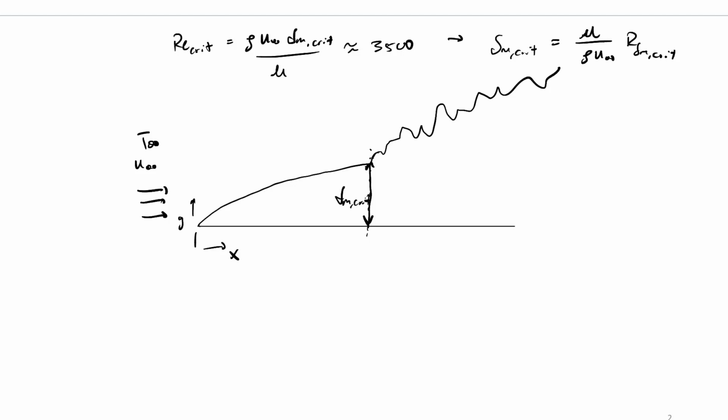It's sort of cycling, you get these eddies. And so this boundary layer no longer grows nicely by this diffusion process. It's growing by a chaotic process. So on average, it's growing more quickly. If you look at any sort of local position, it's very chaotic and unstable. But okay, so you're growing. So we go from laminar here to turbulent here.